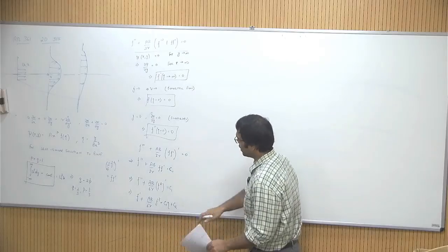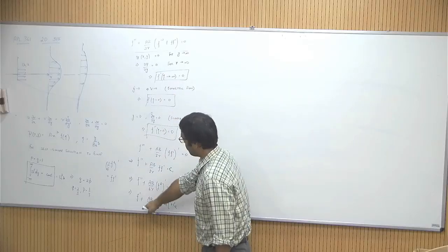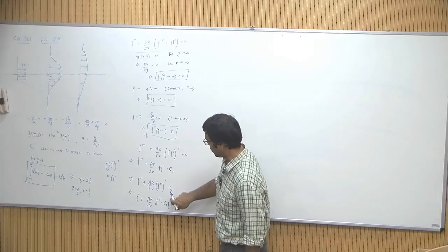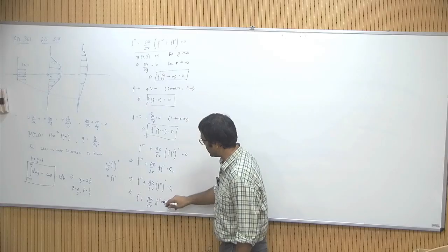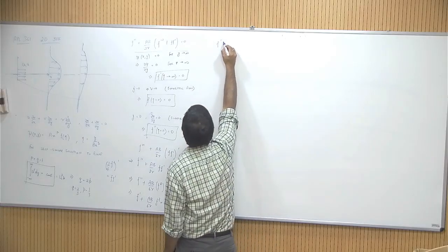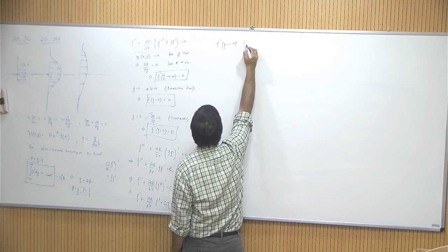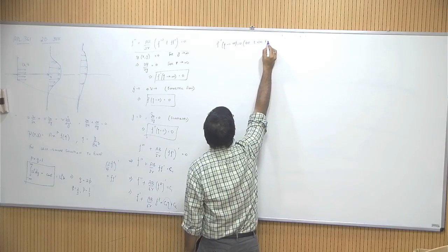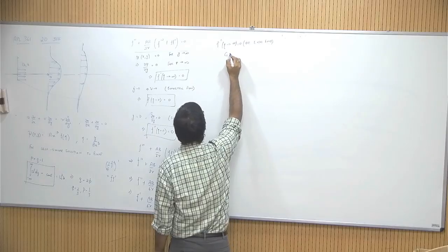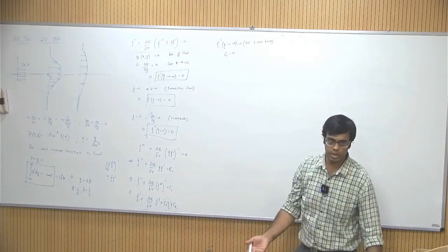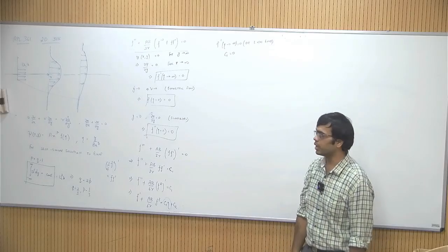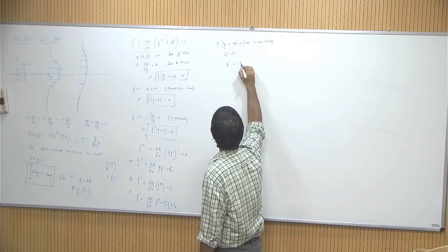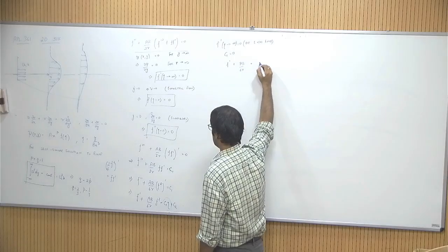Okay, now from here you see that for f prime to be 0 as eta tends to infinity, you realize that c1 has to be 0. So for f prime, as eta tends to infinity, or even finite, c1 has to be 0. Okay, c1 cannot be some finite quantity. So that means we have to solve f prime plus ab by 6 nu f square equals some c2.